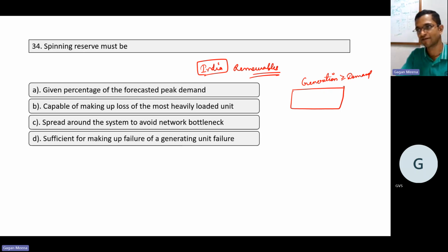If it is too hot, then everywhere in the Indian subcontinent it's too hot. The wind differential, the pressure difference, is less, so the wind speed is less in the subcontinent. Similarly, when it's too hot, the efficiency of solar panels reduces. So the output of both wind and solar reduces during very hot and very cold climates. In cold, insolation is less, so solar output is less. The wind, same thing happens, the pressure difference is less if it is too cold.